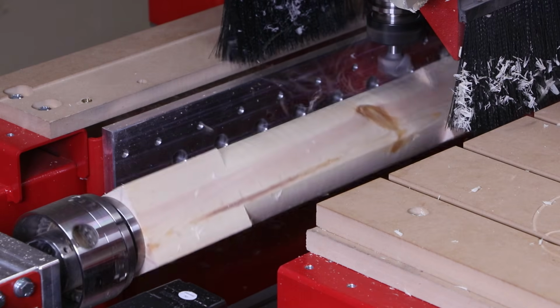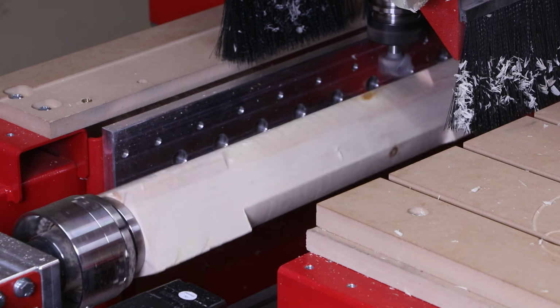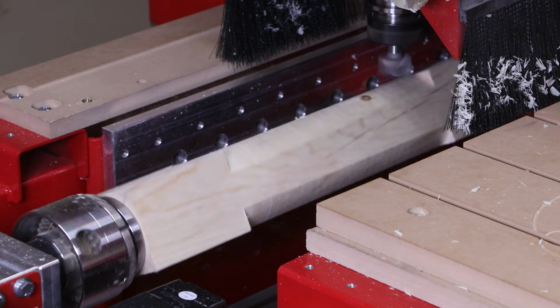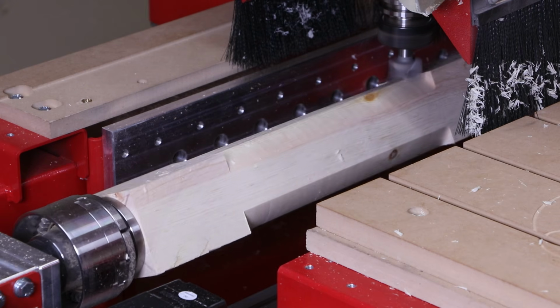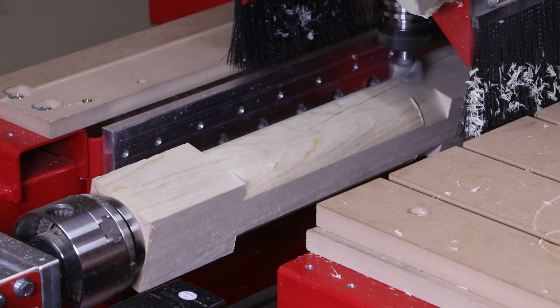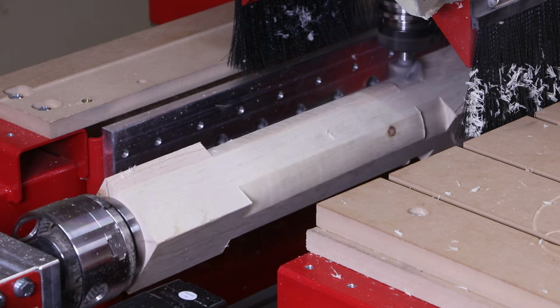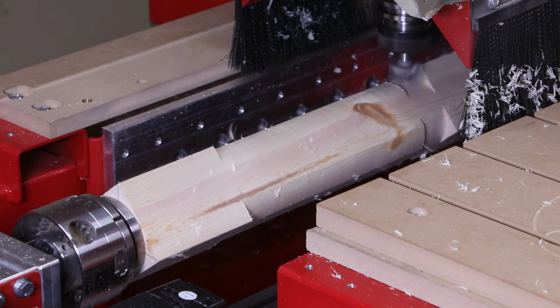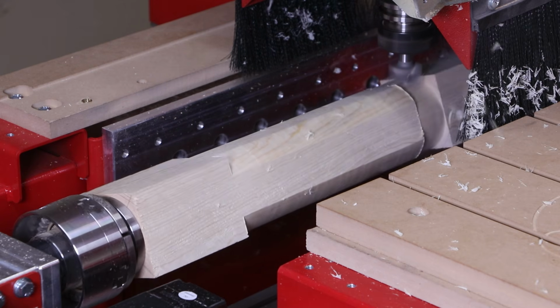Once it reaches the end position of our turning round section, it squares off the corners once again, but rotating in the opposite direction to again ensure that we're not tearing out the corners on that opposite square face. The surfacing cutter will then repeat this process until it gets to our final diameter of 2.5 inches.